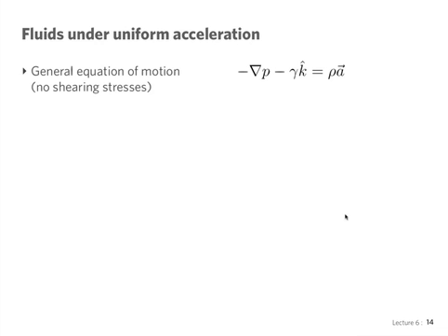And if there's no relative motion inside the fluid, there's no viscous forces. And if there are no viscous forces, then we're again in the same situation that we were for this whole section of statics, where the only forces involved are pressure and weight. So that's the situation here. So the equation looks pretty much the same. So remember the equation that we had from the beginning of this section. We looked at a situation. We saw